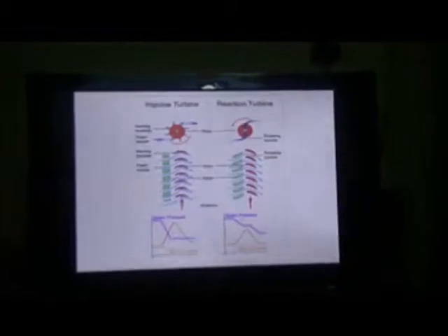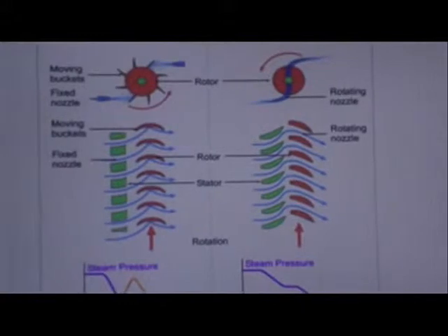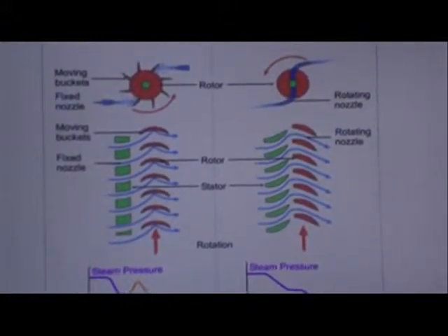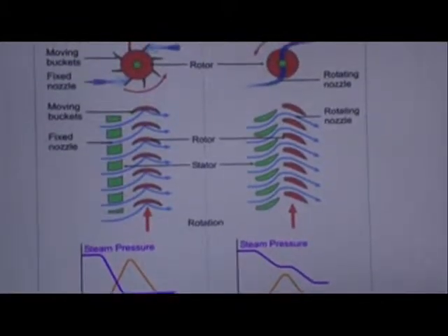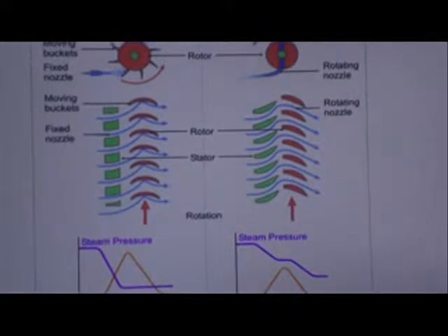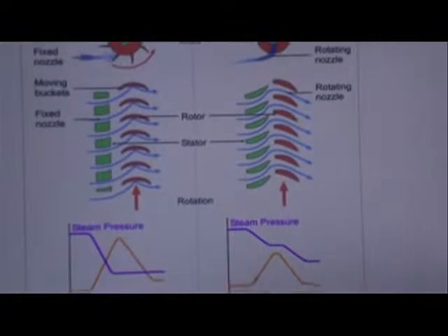Turbo machines can again be classified on the basis of whether the pressure change is absent or present respectively. They are impulse type turbines and reaction type turbines. Impulse type turbines: there is no pressure change of the fluid or gas in the turbine blade. It does not require a pressure casement around the rotor. All the pressure drop takes place in the stationary blades before reaching the turbine. The fluid pressure head is changed to velocity head by accelerating the fluid with a nozzle. Newton's second law describes the transfer of energy. Example, Pelton wheel.